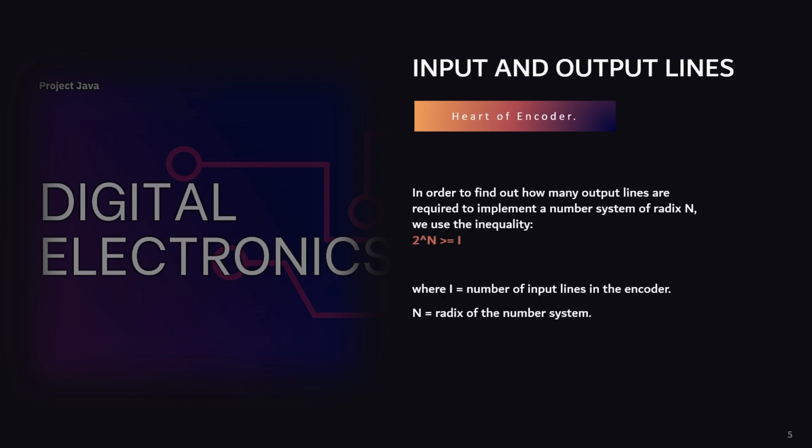Now let's talk about the heart of the encoder, which is the input and output lines. In order to find out how many output lines are required to implement a number system of radix I, we use the inequality 2 to the power n is greater than or equal to I. So this is how an encoder looks like. I'll obviously show this diagram on the board.